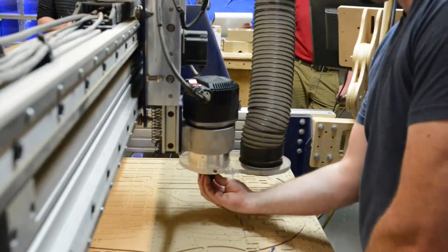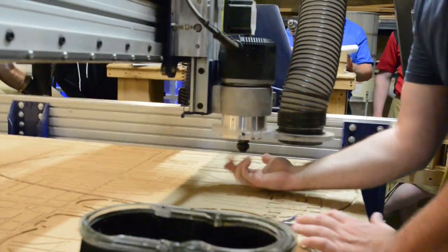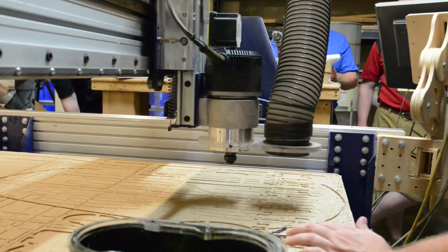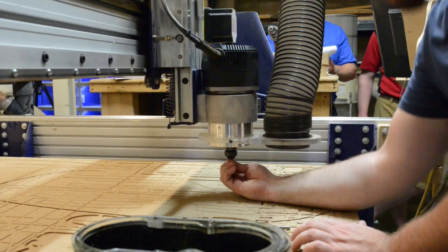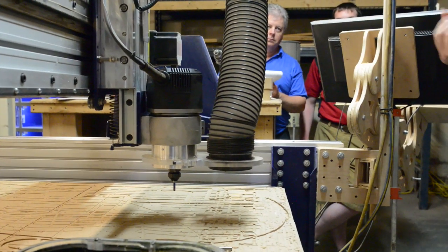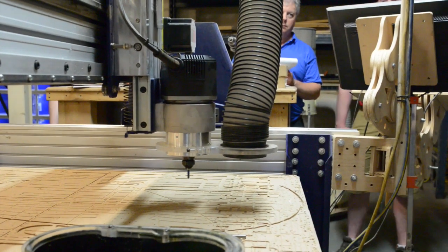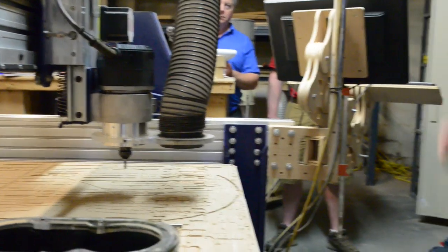So you've got to grab that. You can screw it on first. You don't have to put the bit in there. Just right below there, screw it on until it's hand tight. Don't tighten it down until you put the bit in. Put the bit in a little bit. Make sure you've got at least a 1/2 inch up there. Probably get as much as you can while this cutter head's still out there.